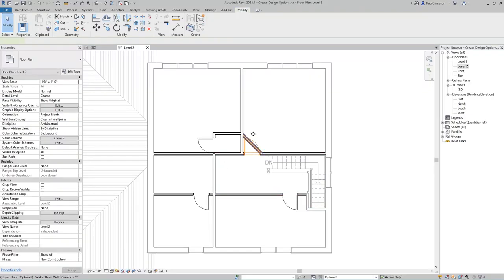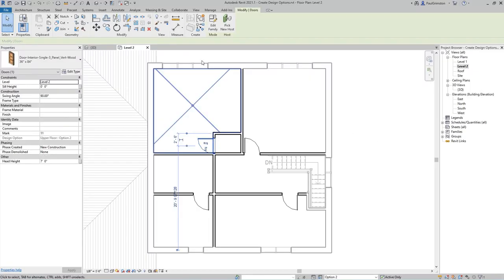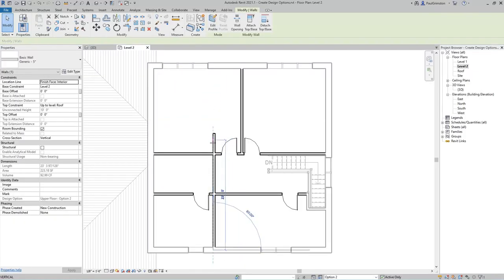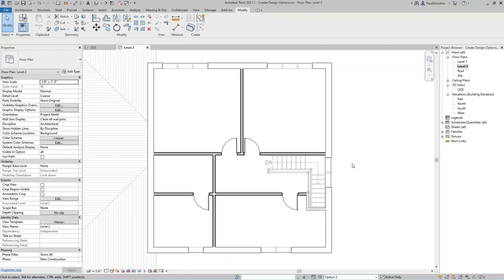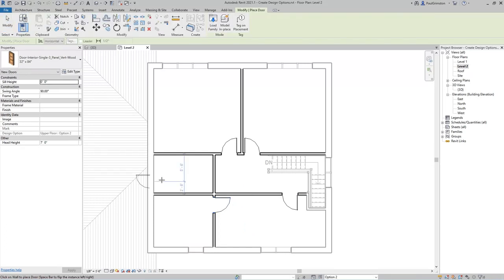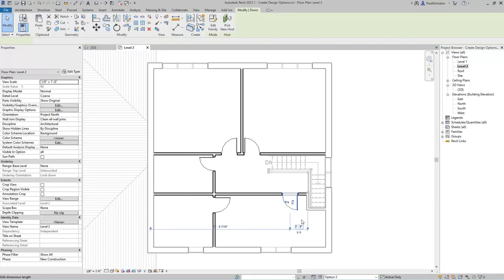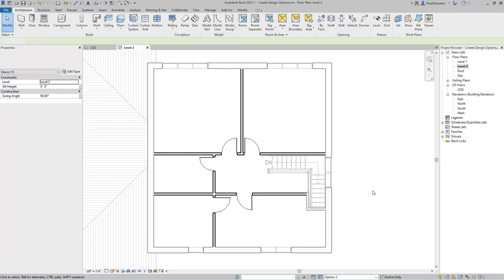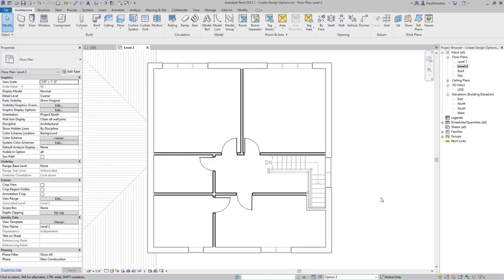Now we'll delete this angled wall so that we have our first design change. We'll pick a new host and place this door on this side of the partition. Now we can delete some of these walls and stretch these back and create our alternative layout. This door will move into this wall here, and we'll create a new door to go into this room. Finally, we'll take this door and move it to a different position in the wall, so that we now have our alternative layout.